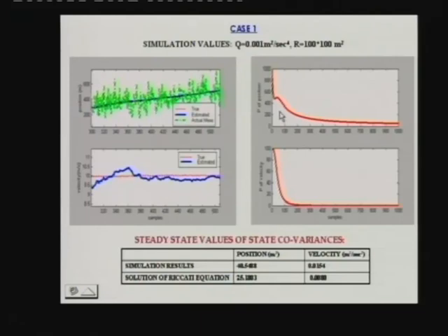Now here, just to show the asymptotic results, we have plotted the diagonal elements of P, that is with estimation between 0 and 1000 points. You can see that as these state estimates become better and better, the state error covariance sharply falls and then reaches a steady value. So the P matrix indeed converges. This is an observable system, right? Controllable as well. And note the convergence: about 300 to 400 samples it has mostly converged. It has come to about 90-95% of the steady state value, right?